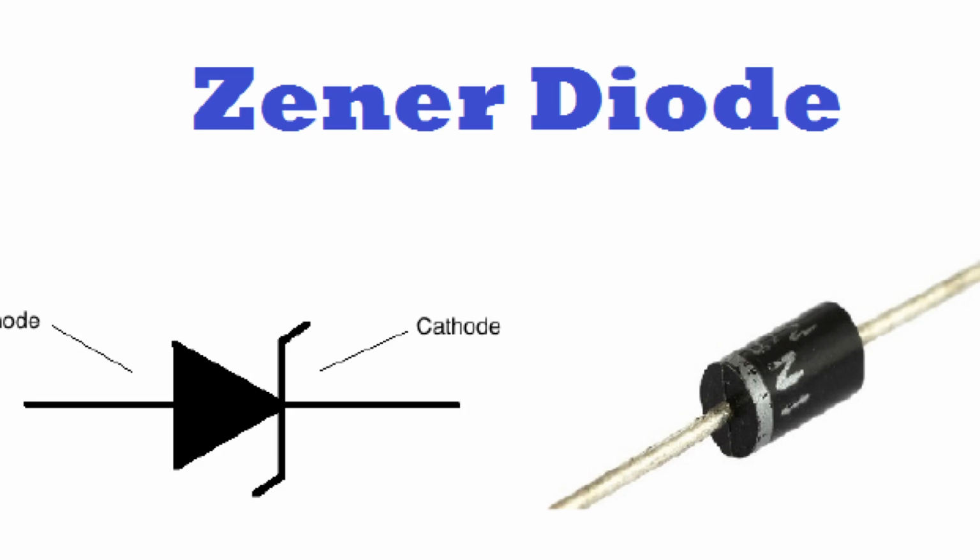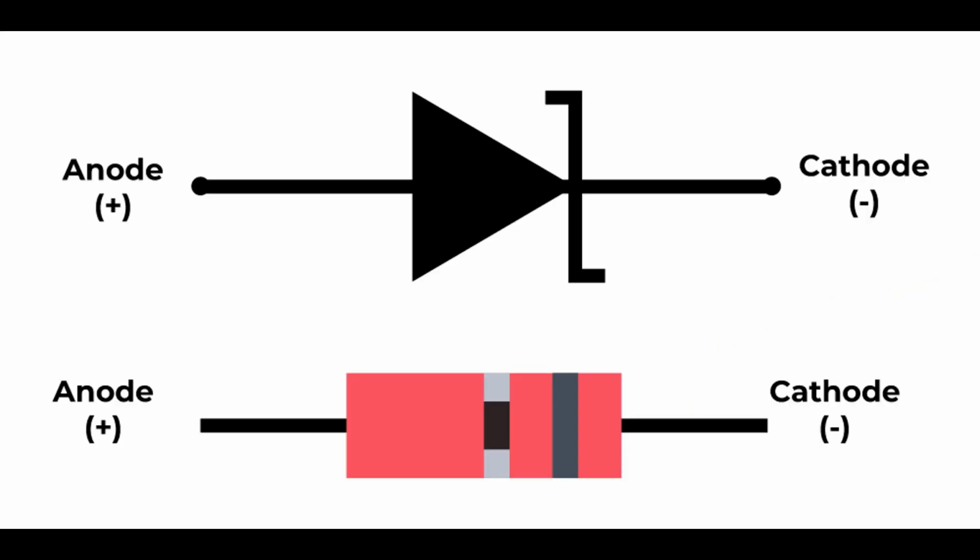Transient voltage suppressors, TVS diodes, are semiconductor devices specifically designed for overvoltage protection. They respond quickly to transient overvoltage events and provide a low resistance path for the excess current. Overvoltage crowbar circuit. The crowbar circuit is a protection circuit that uses a thyristor or other switching element. When an overvoltage event is detected, the crowbar circuit triggers, short-circuiting the power supply and protecting downstream components.